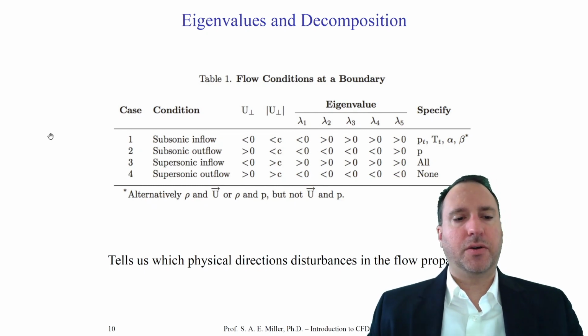Now, in a fluid or domain in 3 dimensions, if there's a disturbance in a flow of uniform velocity or Mach number, then information will travel upstream and downstream. Typically, in a 3-dimensional flow, there'll be so-called 5 eigenvalues. And this is no surprise because, of course, there's 5 major equations in motion in the compressible flow. These eigenvalues are positive or negative depending on the Mach number of the flow. We'll show these results in a second, but first I want to explain the physical connection.